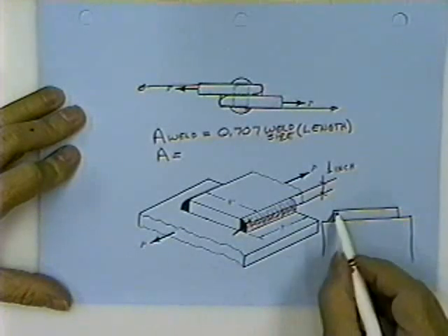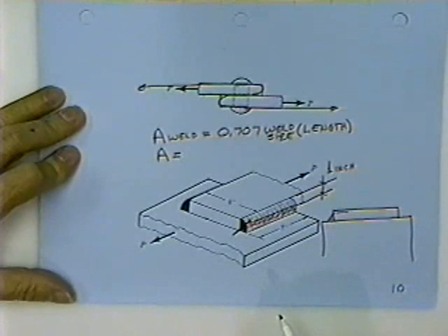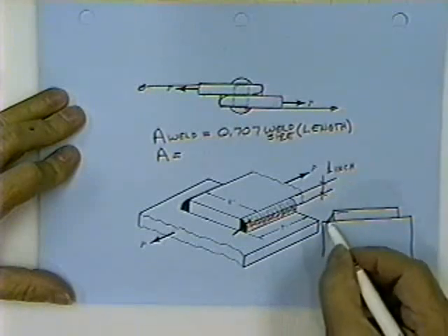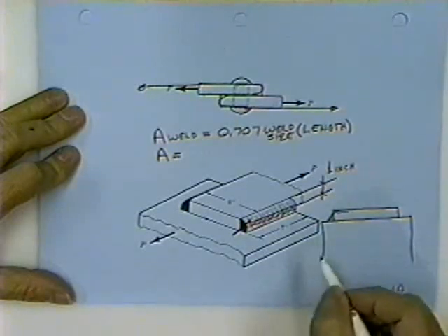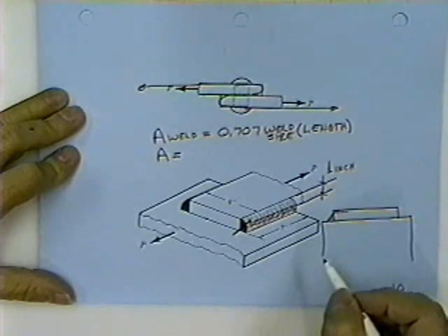They want this weld height to stay down below that corner by about 1/16 of an inch. The reason is that's for inspection. If you let an unscrupulous welder get in there, he will heat the weld up so badly that he'll just burn the corner off rather than really build the weld up to the full 1 inch size.